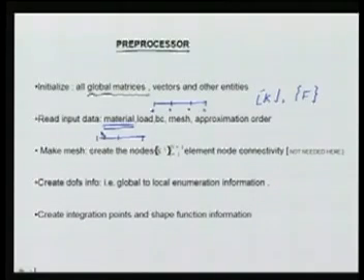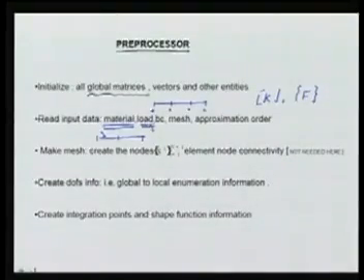So how are the material properties given? In terms of the coefficients of EA(x), that is EA(x) is equal to C0 plus C1x in a particular material domain. So in each material domain these values have to be given. Similarly, the K0 has to be given in each of the material domains. Similarly, I will have to give the load data, that is the distributed load. How is it varying? Is it varying in the whole domain as a linear, quadratic or constant, or is it applied piecewise? In a small region it is something, in the other region it is something else. Everything has to be given upfront.